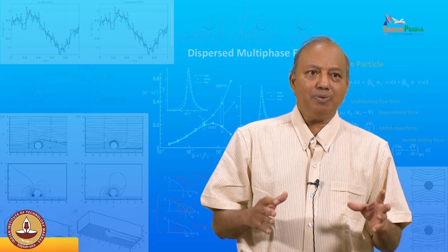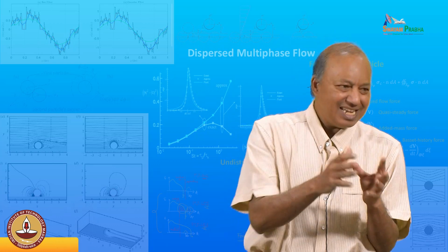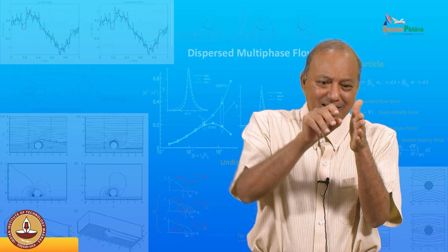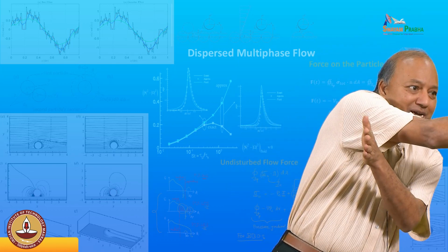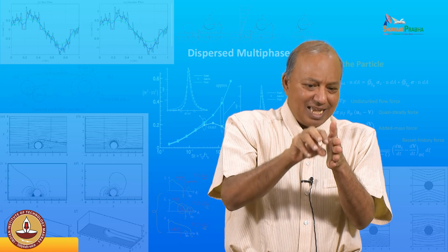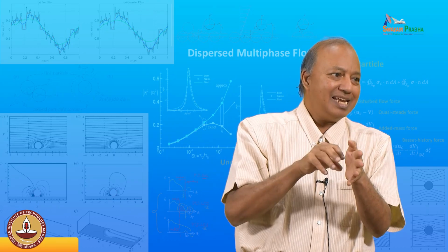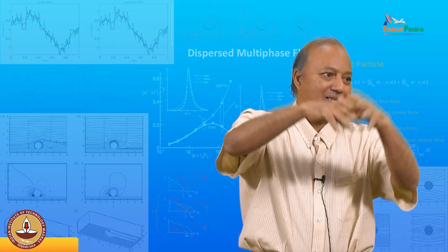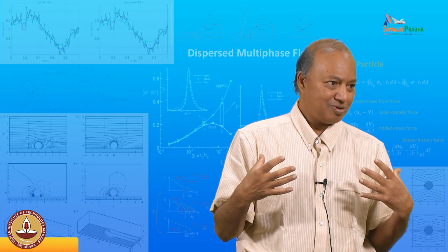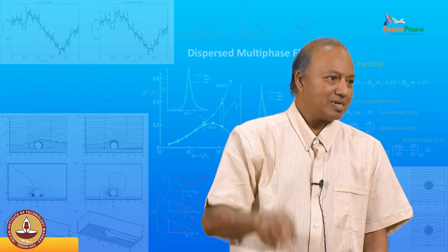The box size will be such that a particle in one time step cannot go beyond the neighboring boxes. You choose the box size in such a way that every particle that was in a box can at most be in the 9 boxes, or the 27 boxes that are surrounding it in 3D, so that it can move only within the box or out to the neighboring box.